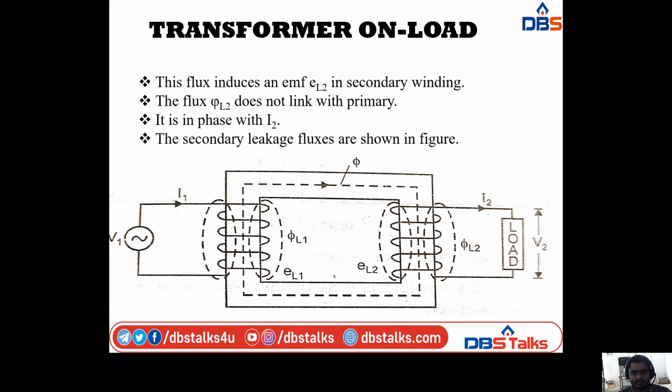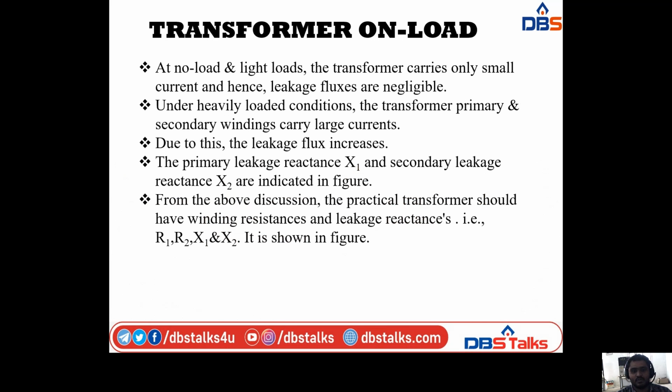At no load and light loads, the transformer carries only small current, and hence leakage fluxes are negligible. Under heavily loaded conditions, the transformer primary and secondary windings carry large current.